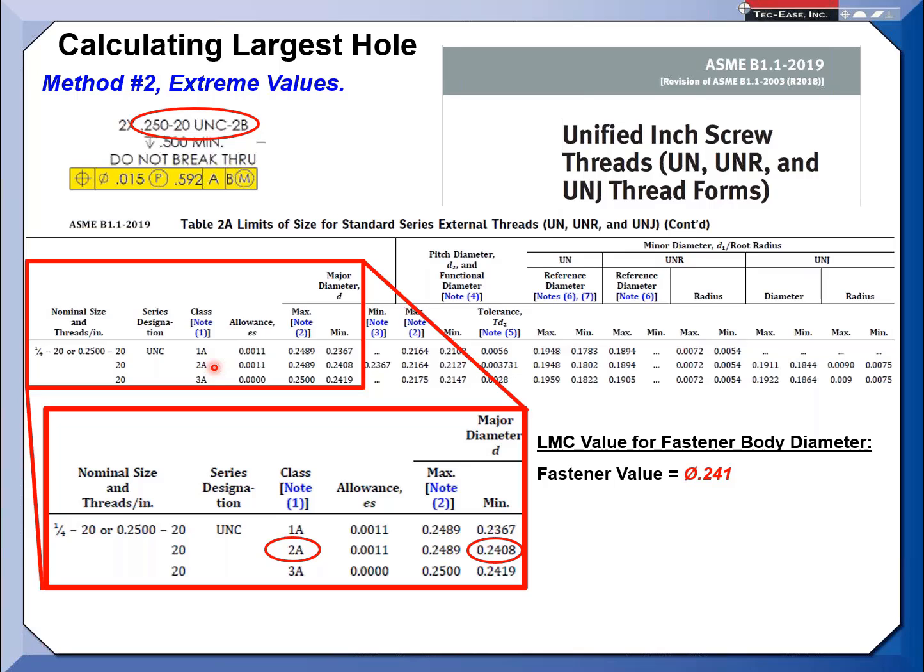We were very critical of threads, and we were not using M's, and we'd actually come off the pitch diameter. Typically they were class 3, very tight fitting hardware, with minimal shift between the internal and external features. But that's design intent. Good point. You can use them on threads. The standard does allow it. Absolutely, that's a good question.